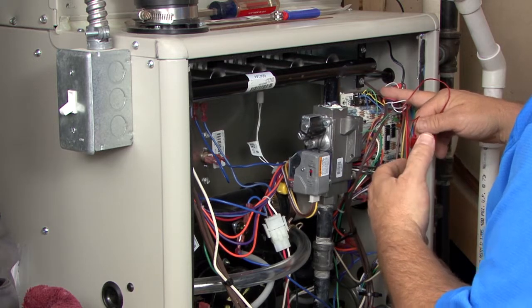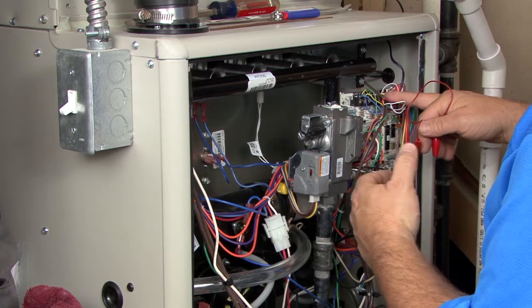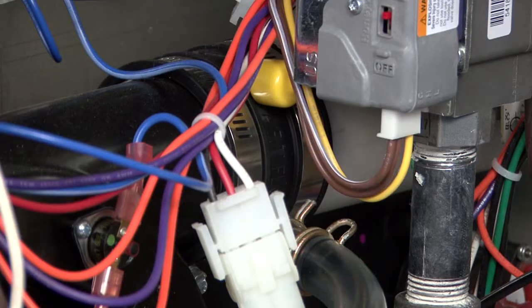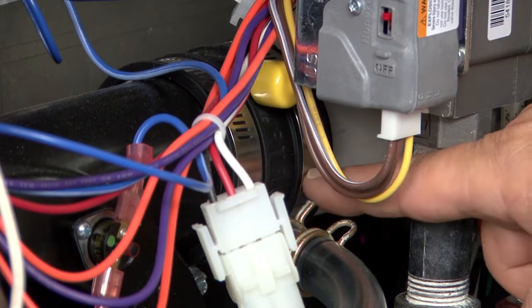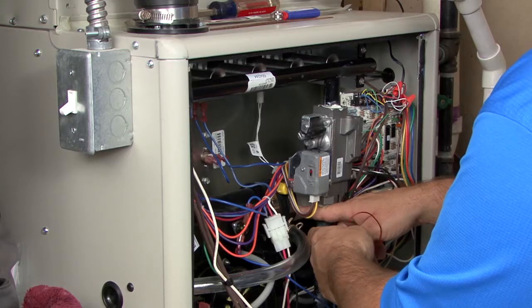And then lastly, once I'm all set up for that, before I turn the power back on to get that blower to run at that speed, the other thing I want to do is disconnect the flue pipe. So I'm going to come down here just to the inline drain assembly, and I'm just going to undo the 5/16 screw down there, and then I can just reach back and pull that flue back out of the way.